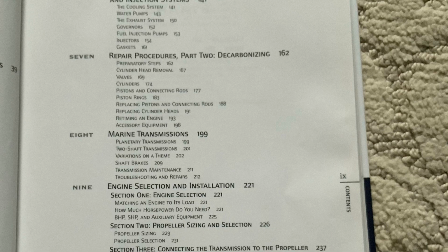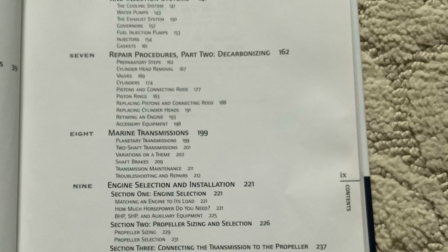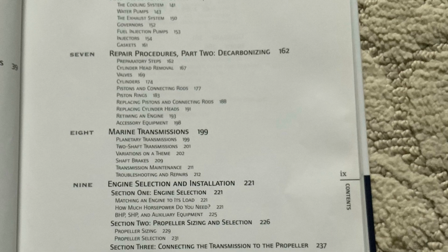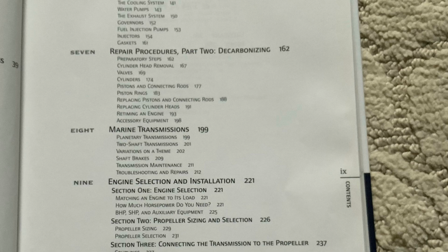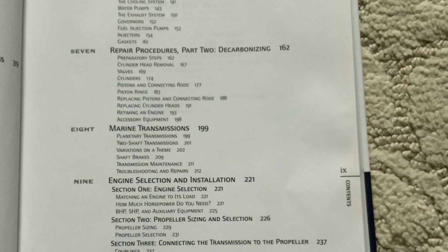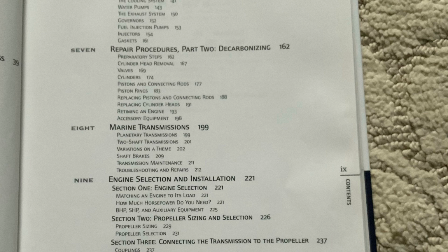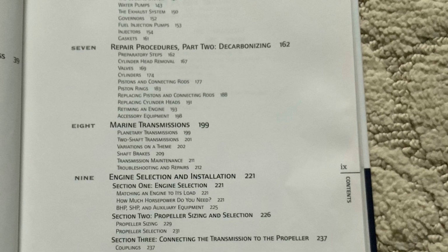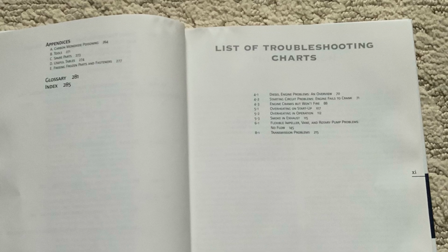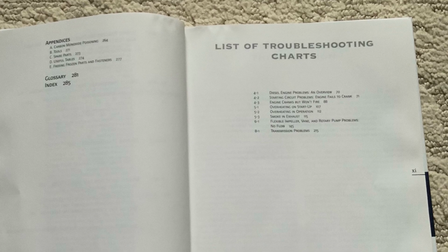This enables the thermal efficiency of the engine to be determined, i.e., how much of the fuel's heat energy is being converted to usable power. The average diesel engine has a thermal efficiency of 30 to 40%. In other words, only about a third of the heat energy contained in the fuel is being converted to usable